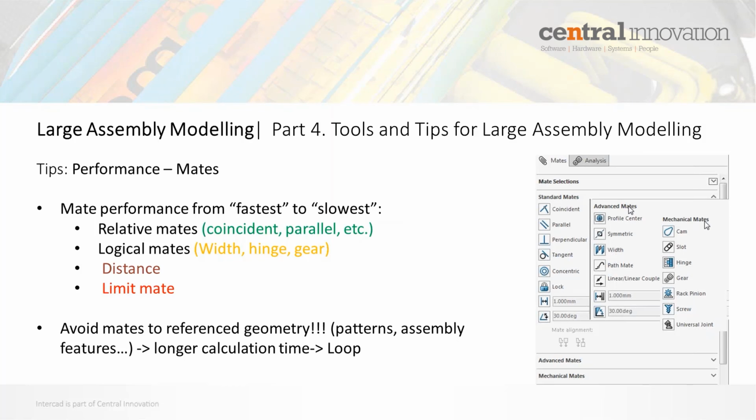And I guess my last tip there is to avoid mates to reference geometry, so patterns, assembly features, guaranteed to create longer calculation time and also result in context circular reference issues.